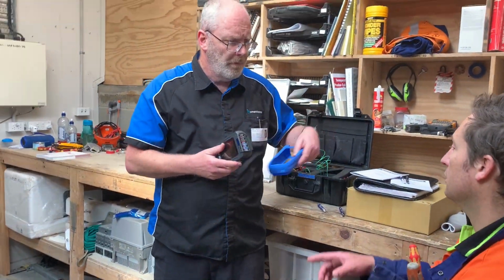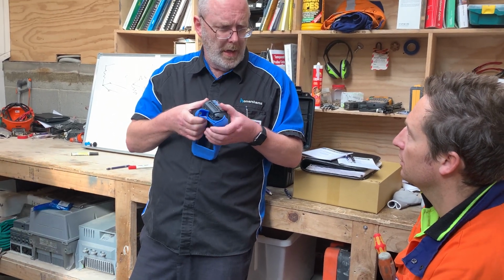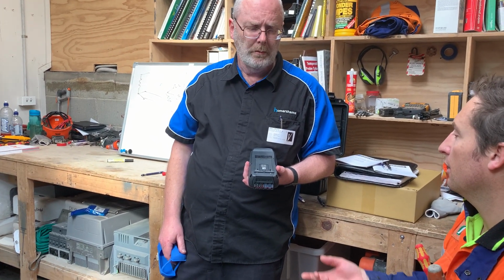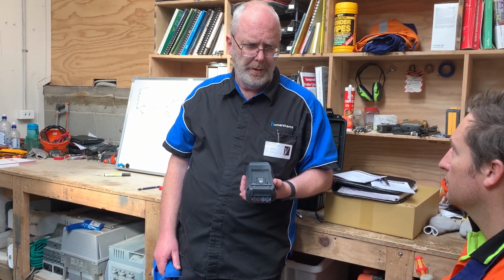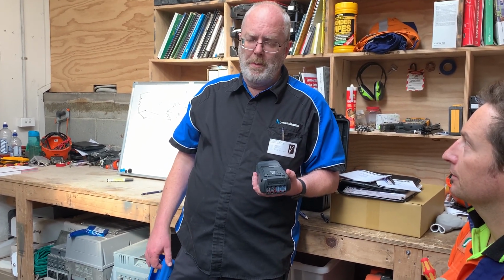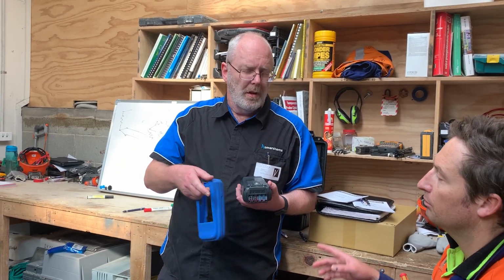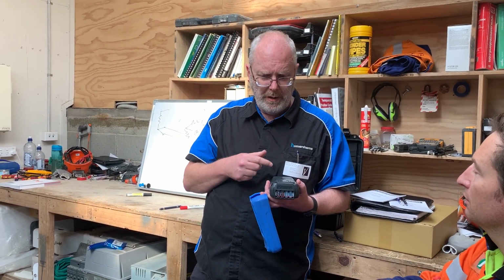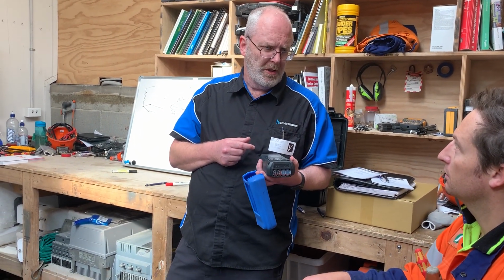The question I did have is that cold junction compensation factor based on the ambient temperature. Yes, it's based on that PRT. That PRT is the ambient temperature of the room, right? Now if I point a PT100 into it, it should be pretty close to the ambient temperature, isn't it? Well, if it's a PT100, it's not using cold junction; it's measuring resistance. Same drill, but a K-type probe. That K-type probe should be pretty close to the ambient temperature of the room. It won't matter, because of the cold junction.